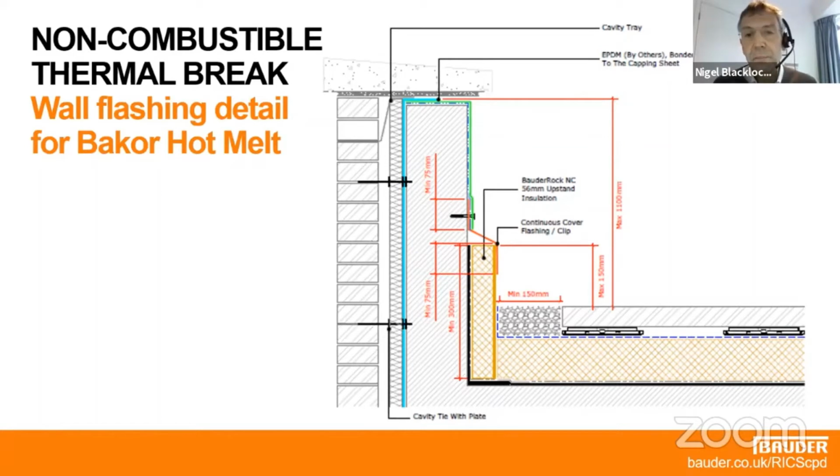So we see here for a parapet, the insulation in the wall actually continues to the top of the wall there of the parapet. But there is this flanking heat loss through that internal leaf. And therefore you need a little bit of insulation on the upstand there. And that's described as being a minimum of 300 mil from the deck upwards. But we always need, as roofing practice, at least 150 millimeters of waterproofing above the finished roof level.